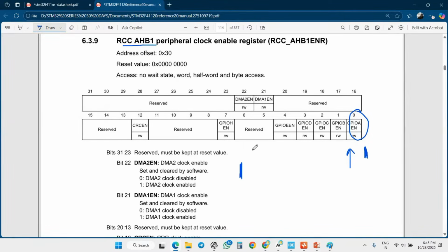If you are shifting the bit, there are 2 parameters: the first operand and the second operand. The first operand tells what you are going to set, like 1 or 0x3 or 0xF kind of thing. The second operand tells how many times you're going to shift. Here, I'm going to set 1 on the 0th position. So how many times do I shift? No need to shift. I just simply keep it 0. So for this bit which is going towards like this, I'm going to use the left shift operator.